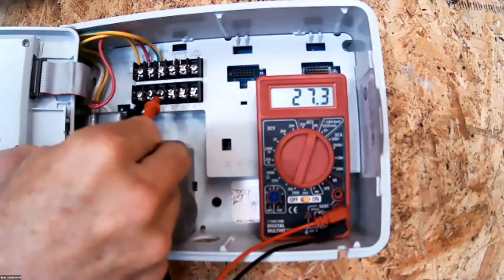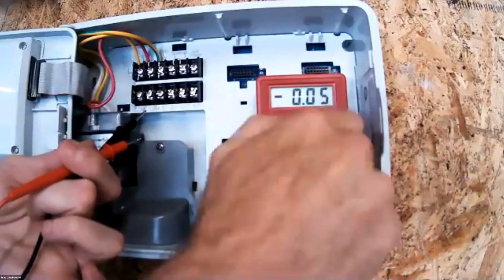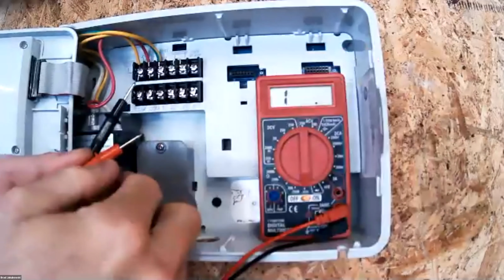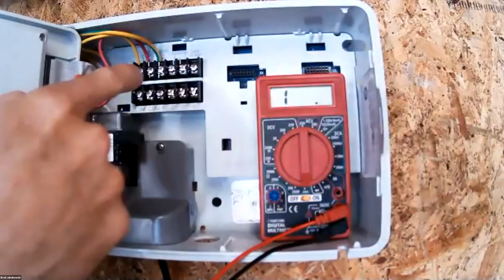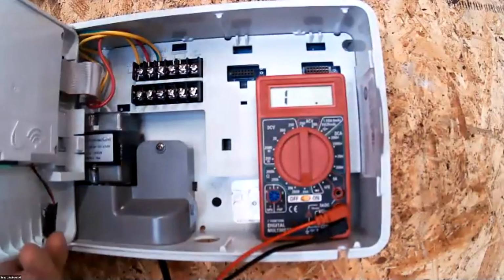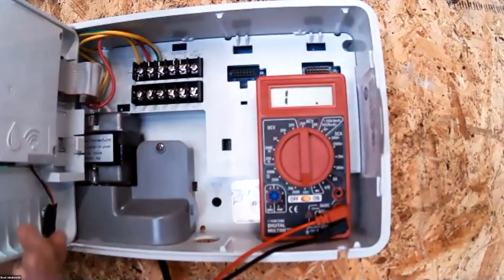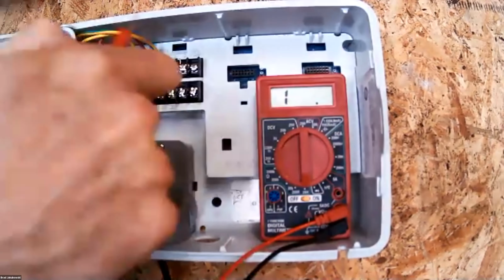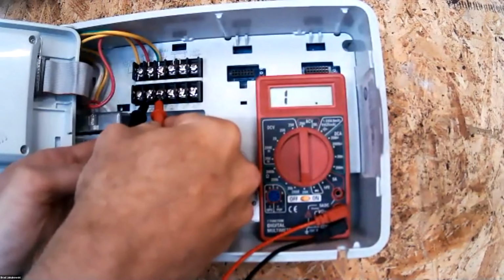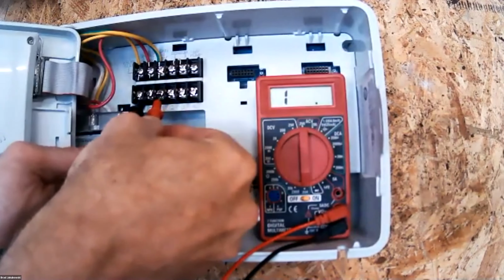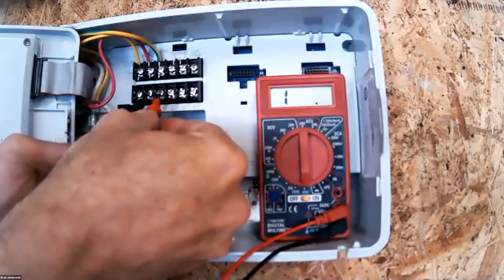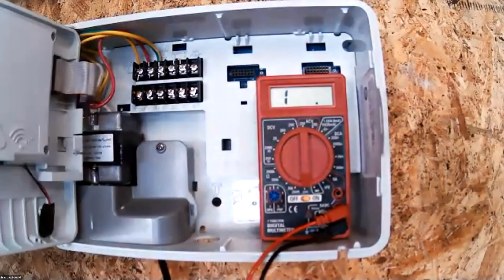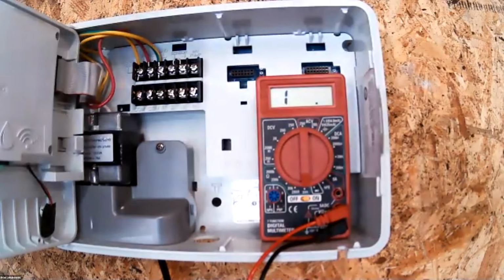The next thing would be to check, if I had a solenoid hooked up to that, and switch over to ohms. We have to make sure that the AC is off, so you would turn that system off, and then double check and see what's going on. Right now we have it open because there's nothing hooked up to that, but that would be the next thing you would want to check. So there's a number of different things that we can do with that.